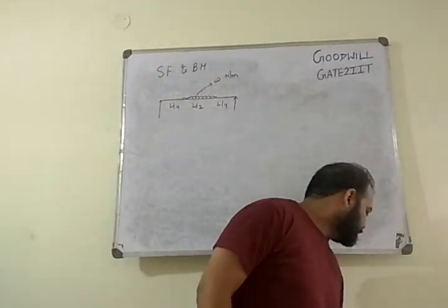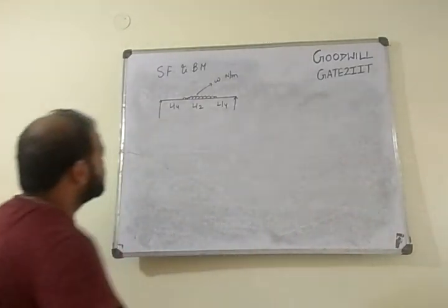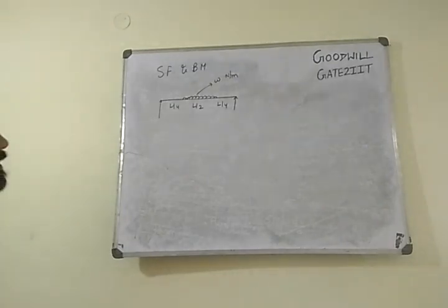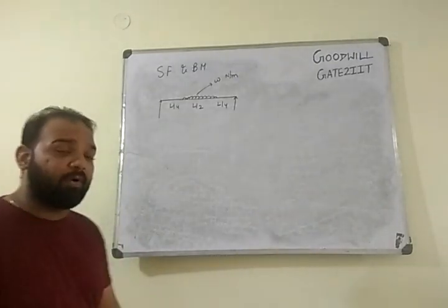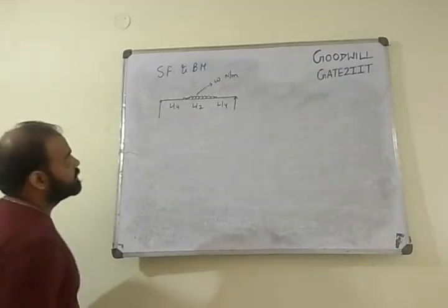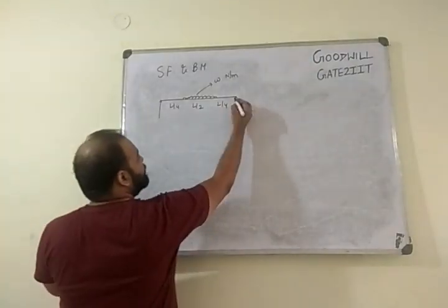Now tell me guys, what you expect? Shear force and bending moment diagram. What first thing we should do? Calculate the reactions, because a simply supported beam always needs what? Reactions. So we'll draw a reaction here. Tell me what should be the reaction.